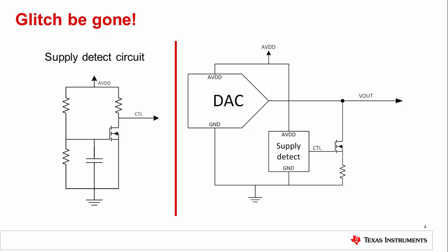Software is not required if a supply detect circuit like the one shown here can be implemented. The sizing of the resistors will change the point at which the supply detect circuit turns on and off.